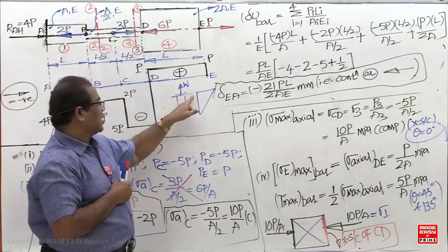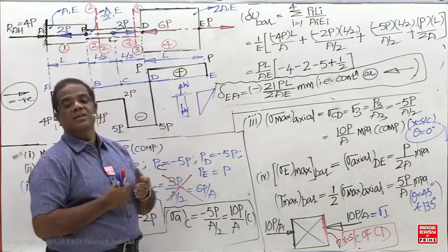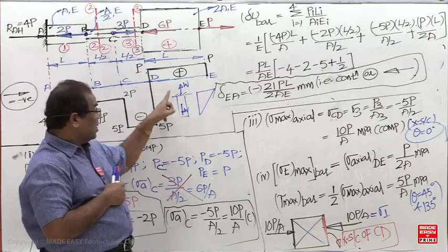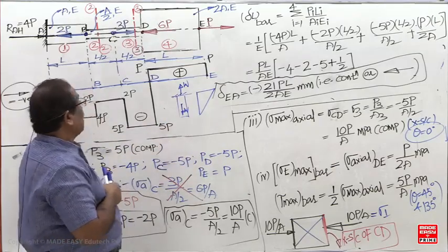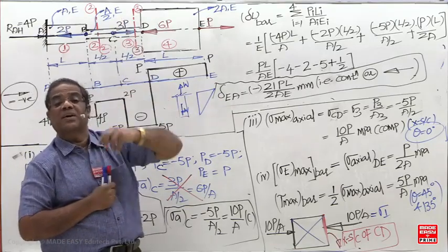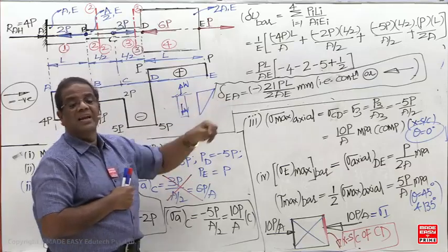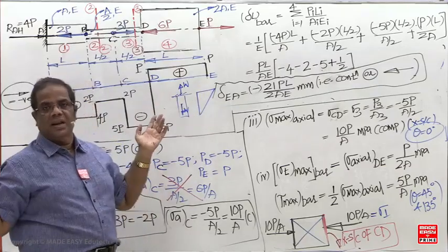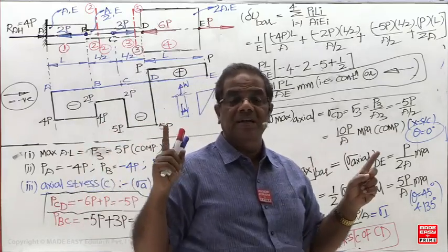So many axial loads are only one axial load. So now you are getting a vertical line or horizontal line? Horizontal, because member is vertical. Your longitudinal axis is a horizontal line. Normally longitudinal axis is a vertical line. In this case, it is a horizontal line. That's why ALD, SFD, BMD consist of vertical lines, but here the longitudinal axis is vertical, then ALD, SFD, BMD consist of horizontal lines. So try to remember that.